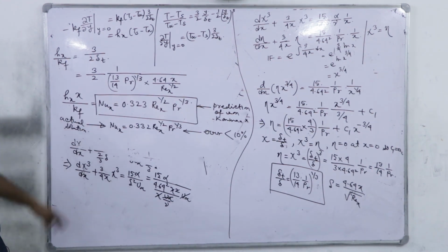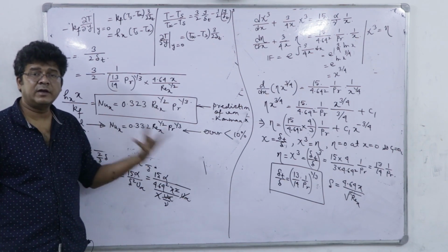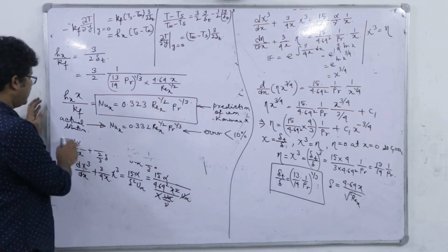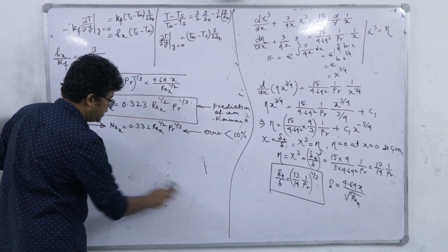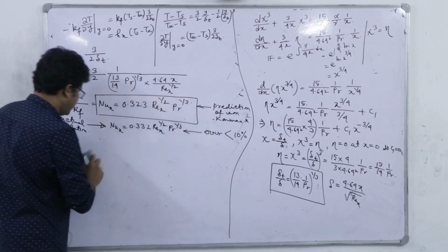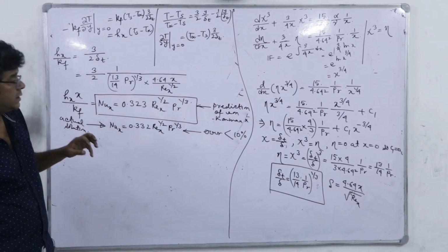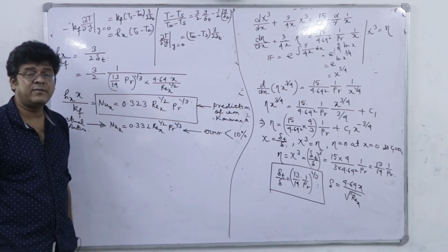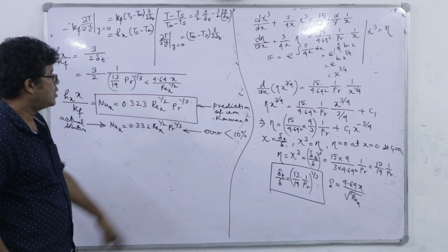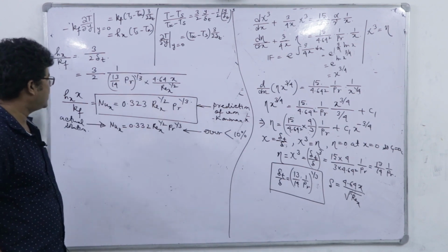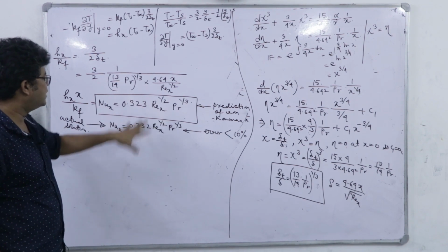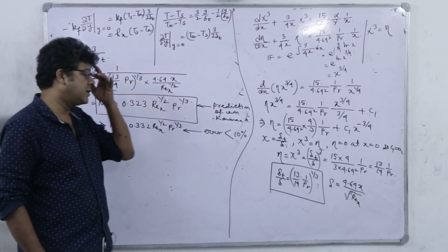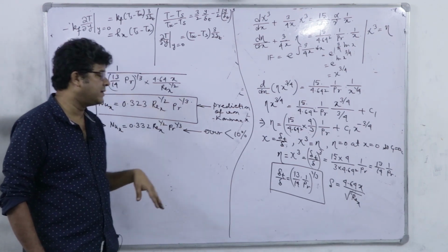but here we have to go for this numerical solution, because analytically it is not entirely possible, because as we know that Blasius solution is finally a numerical solution, whereby similarity we reduce it to a third order nonlinear differential equation, and from there we have to go for numerical solution in order to predict this delta to be equal to 5x divided by under root of Rex. But von Karman gives you an analytical solution. So, this is the difference, and here again the error is less than 10% as obvious. Okay. So, von Karman and this prediction is quite satisfactory.